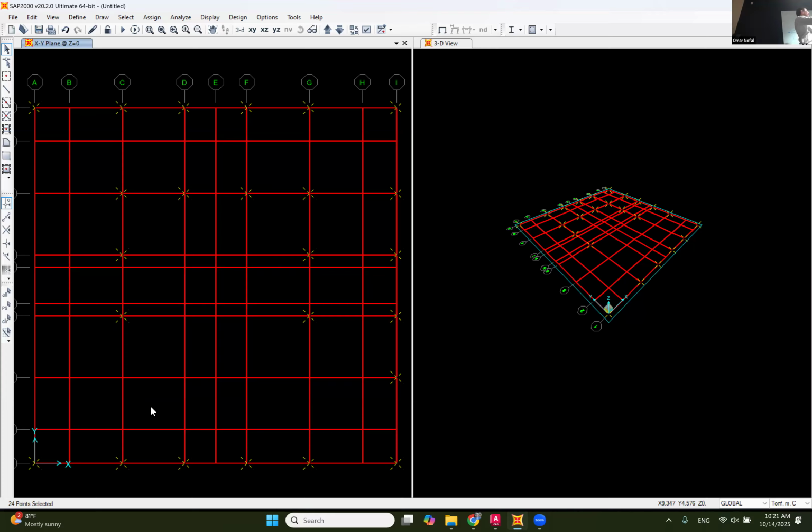Because the thing is, it's all about these joints. It doesn't matter what is inside here. It's all about these joints where all the calculations happen. Like if I do this, select the points, and it selects this. Yeah, that's your question. So it doesn't matter, because when we assign hinges we only assign to a joint. Okay. Okay, so yeah, I'm selecting here.